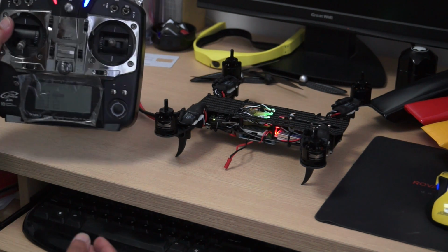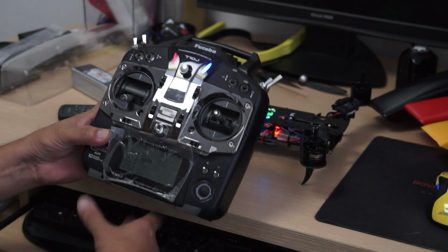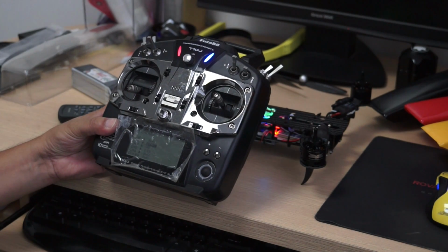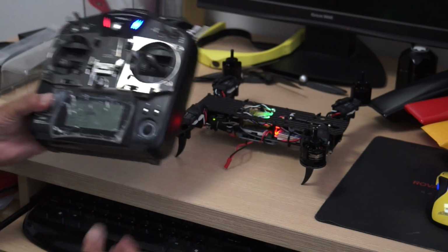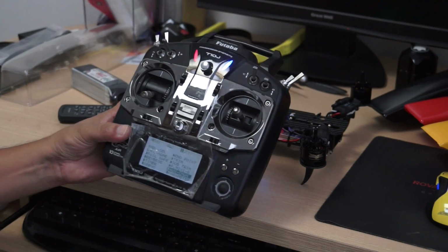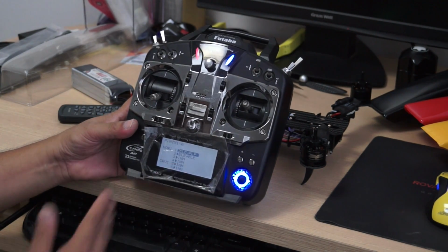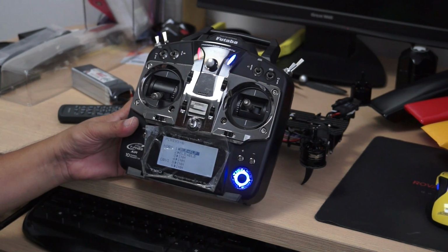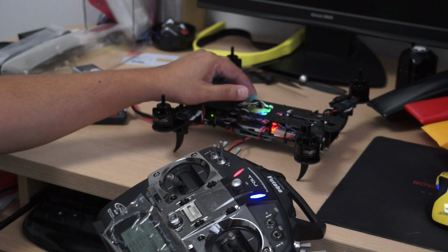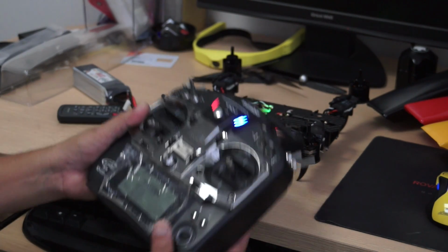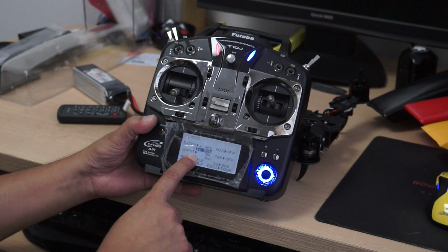Now let's talk about the programming or the mixing. So this was the auxiliary channel setup. Switch C for flight modes, and DT5, sorry, not switch, DT5 is for the fixed tilting, that is trimming on the tilting. Now let's come to the programming mix. What you want to do is create two programming mixes. One is to use the dynamic rotor tilting. As you know, we have connected the servo to channel 6. So we are going to create a mix which is elevator to channel 6.